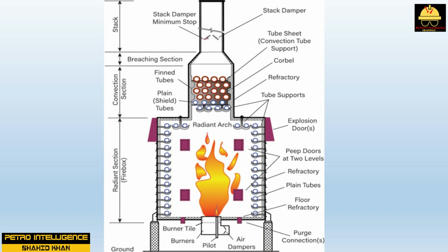Convective heat transfer to the process charge accounts for about 30 to 40% of the total heat energy picked up in the furnace. This area is often referred to as the convection section. It is best described as the upper area of a furnace in which heat transfer is primarily through convection. Feed is introduced into the furnace through these tubes and exits out the radiant tubes.